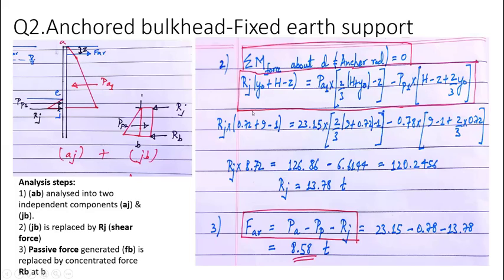So we just put in the respective value of Y0, because Y0 depends upon the relative density. For phi 30 degree it's 0.08 H, and we have calculated 0.72. Then H we know, Z is given, PA1 is already calculated, passive pressure is already calculated. We are able to calculate this shear, by removing this GB. So what is the shear coming at the point of contraflexure?